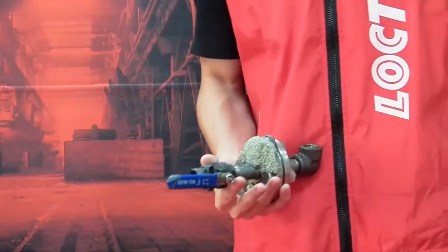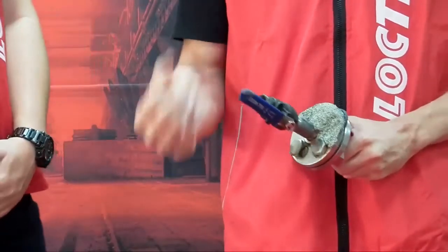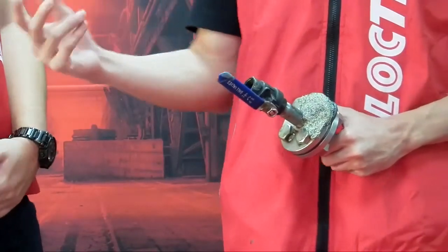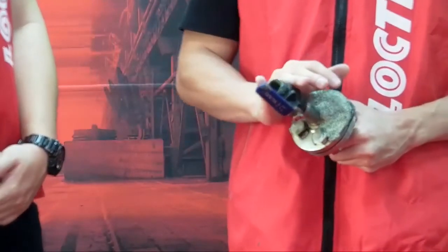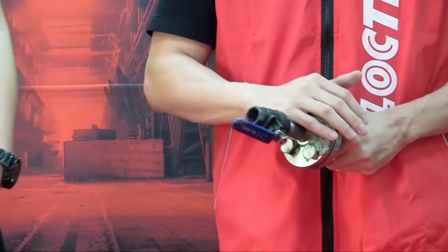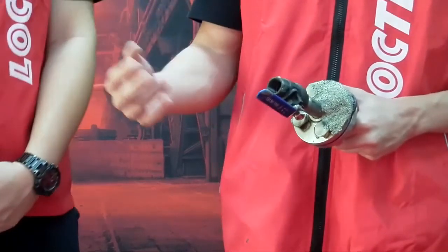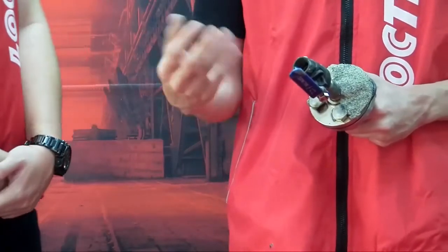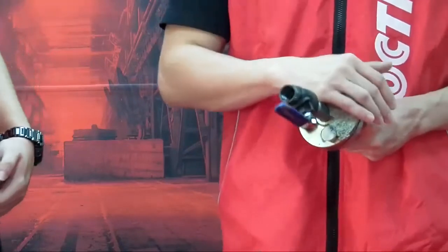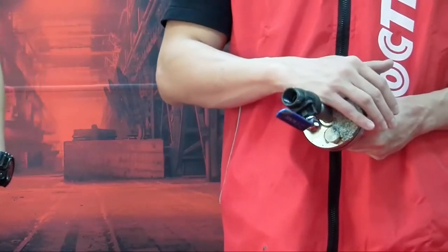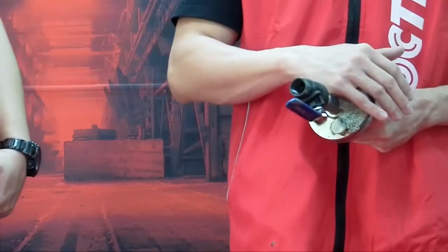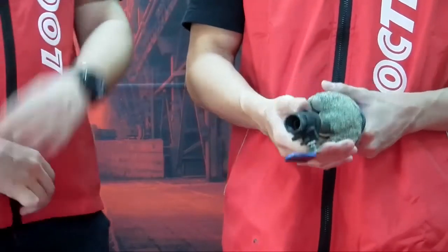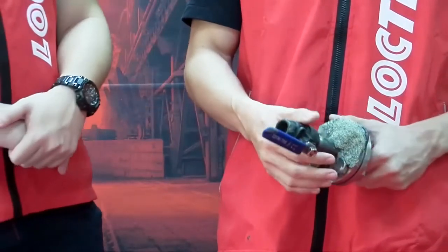Because of the property of this product, it's a very thick paste, so not only can you use it as a protection coating for this solid processing equipment, it also has a sealability advantage on pinholes and leaking areas. In certain areas where we can't do weldment repairs, we can coat this product on the pinholes or the crack area to secure the cracks and prevent liquid from flowing out from the pipeline or the vessels. So in this case, these products can help tackle the leaking.